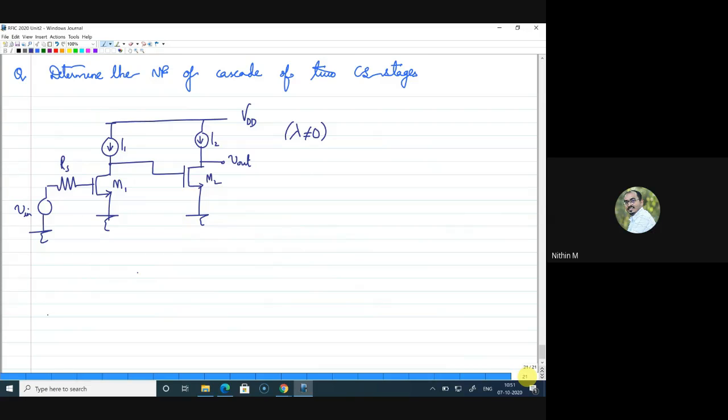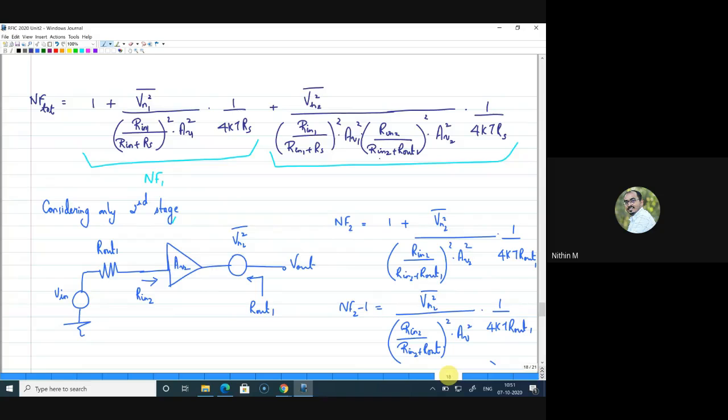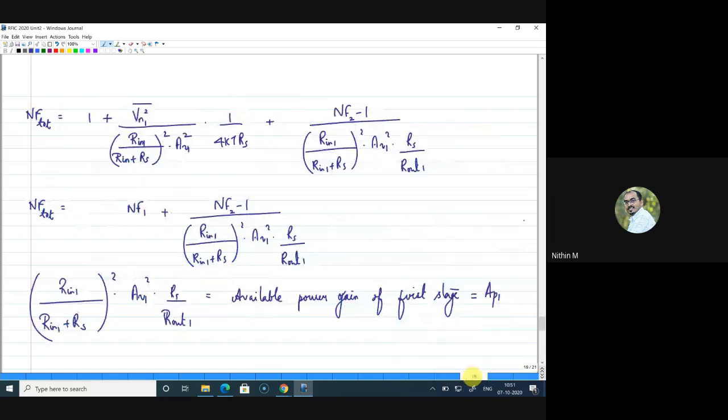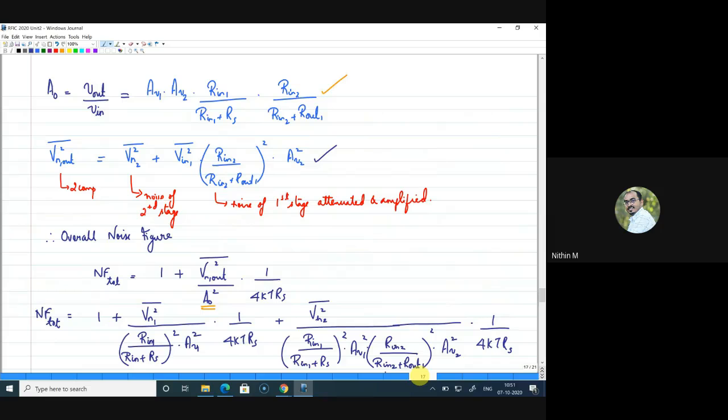So we need to add alpha to our gain. Like we also had alpha, the attenuation factor. Yes, you're right, that we already included in the gain expression. If you remember, we have actually added the attenuation factor here. These two are the attenuation factors, right? Yes, that is already included. What I'm telling is power gain. Why we need to calculate power gain separately is that when the impedances are not equal, then voltage gain and power gain will definitely be different, right?